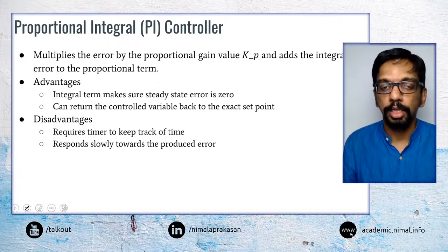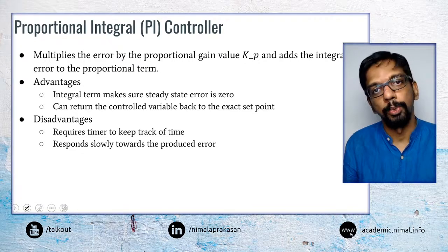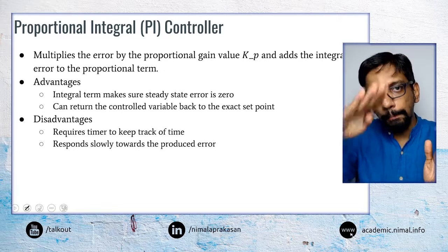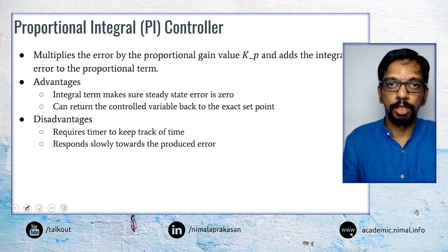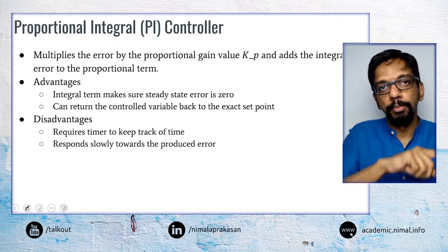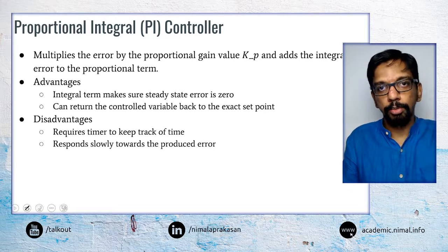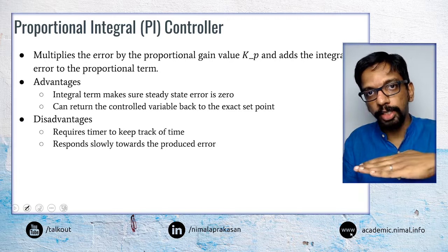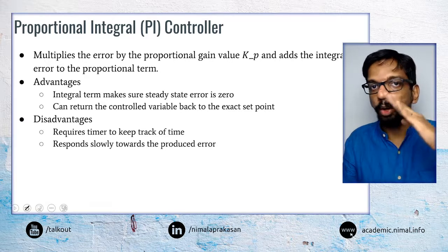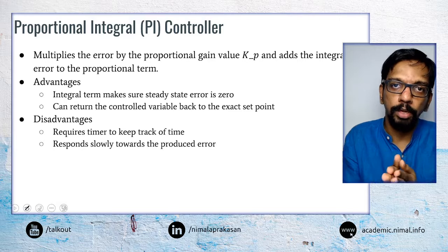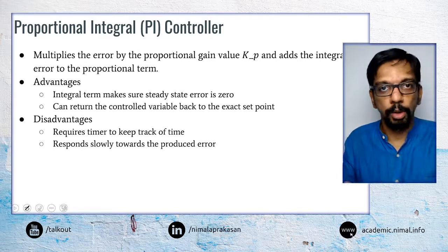So when we take the integral part along with that, this is mainly about how we can dampen the effect over time. So if we start applying the brake over time, the effect, so if we say the speed is reducing, we are going to reduce the amount of brake that we are applying. So that will lead to a point where the vehicle is never stopping.